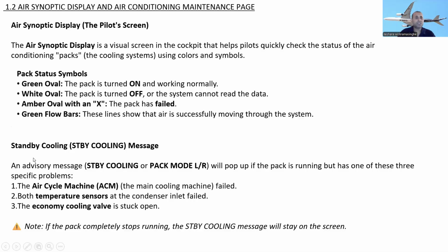Now let's go to the standby cooling message and advisory message. An advisory message like standby cooling or pack mode left or right will pop up if the pack is running but has one of these three specific problems. If there's one of these specific problems, this advisory message will pop up. What are these specific problems?